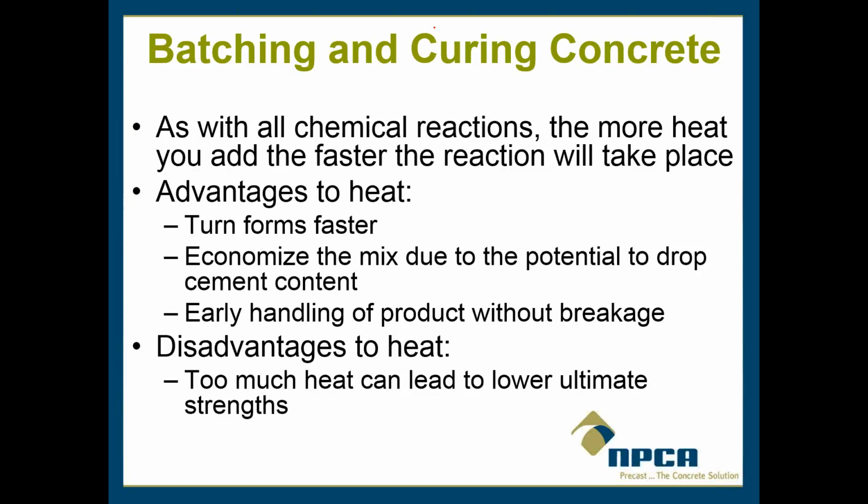Additionally, temperature. Like we talked about earlier, we don't want our fresh concrete at the time of placing to be below 45 degrees, and we don't want it to be greater than 90 degrees, because that's going to affect our hydration reaction and how the concrete matrix, the crystals, form and develop, and how dense and strong it's going to be. So time and temperature, and lastly is moisture.